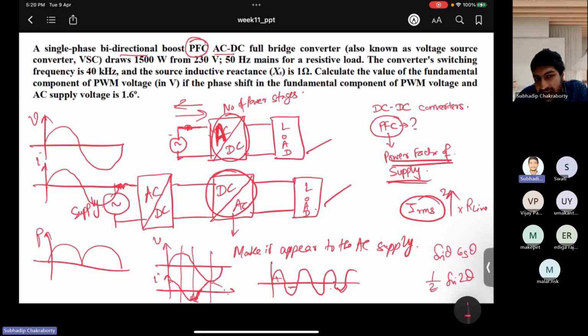And to minimize the power stages, we can embed these two conversion stages from AC to DC and DC to DC into one. That is direct AC to DC. So that is also possible. Otherwise, you will have two stages. One is rectification stage, where you want to convert from AC to DC, and then a DC-DC converter like buck or boost will be attached to that.